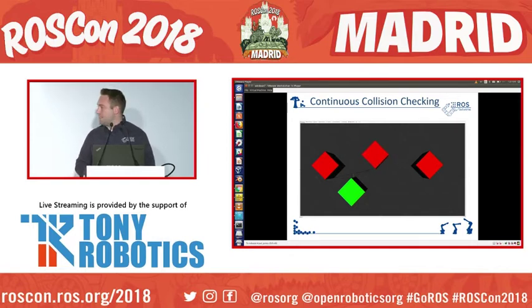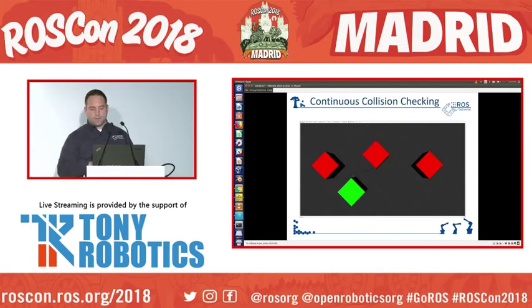So here's an example of continuous collision checking. The green box is the obstacle. The three red boxes are the trajectory. You can see it sweeps the middle box to the left box, and it detects a collision. And it actually pushes the trajectory away from the obstacle to create a collision-free trajectory.